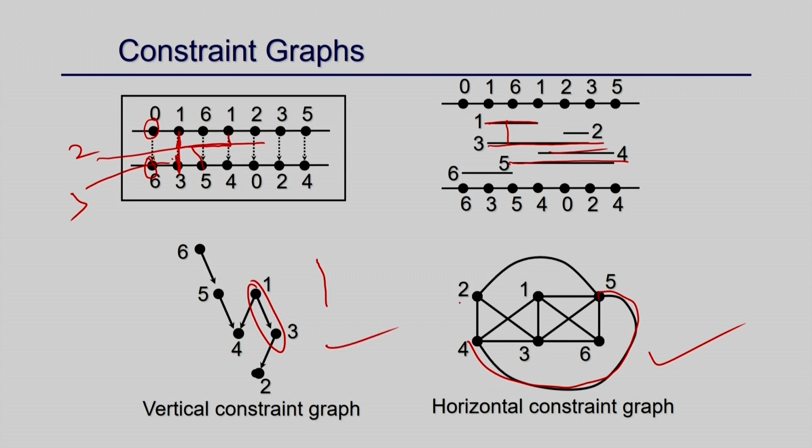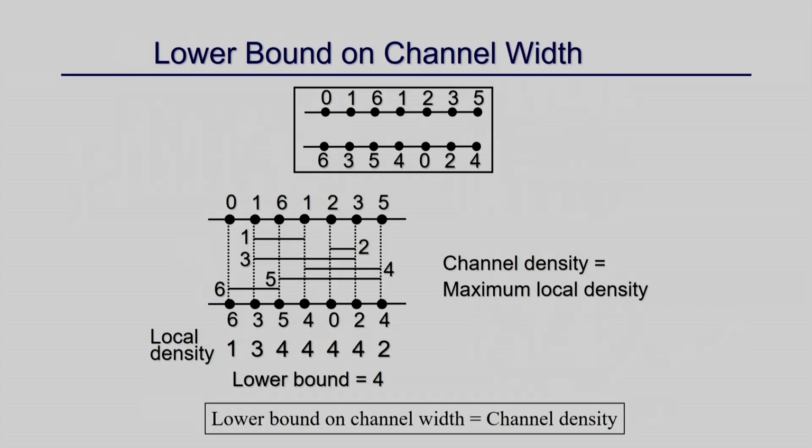So, you can extract those vertical constraints and horizontal constraints, and using them you can solve your problem and identify the minimum number of tracks required using some logic, which is the channel density. There are a lot of algorithms, like the left edge algorithm and other solving algorithms, which can handle dog leg connections or the VHV model. Again, I am not going into the detail of those algorithms, but just to give you the problem flavor, what the channel routing problem is and what is happening here.